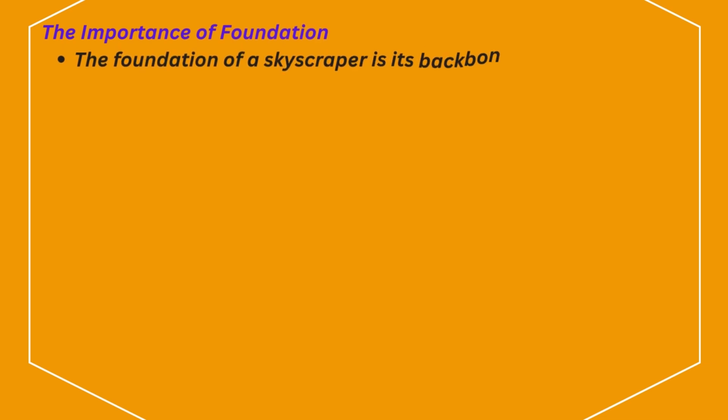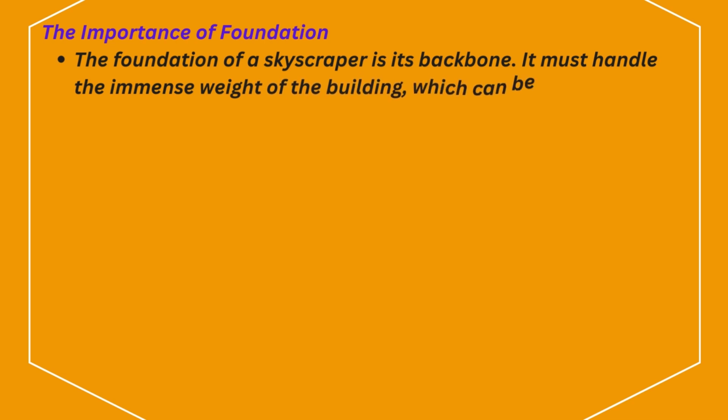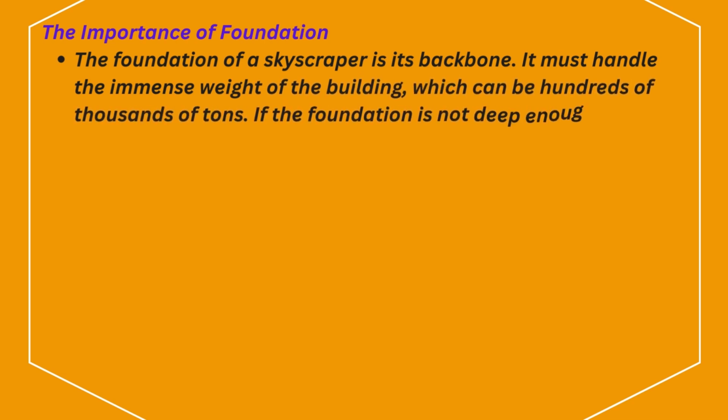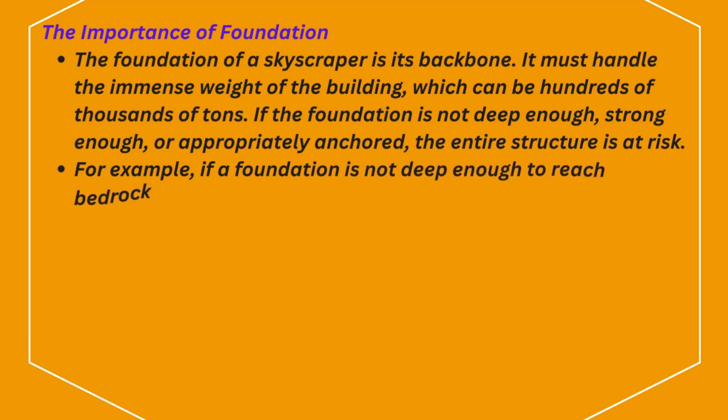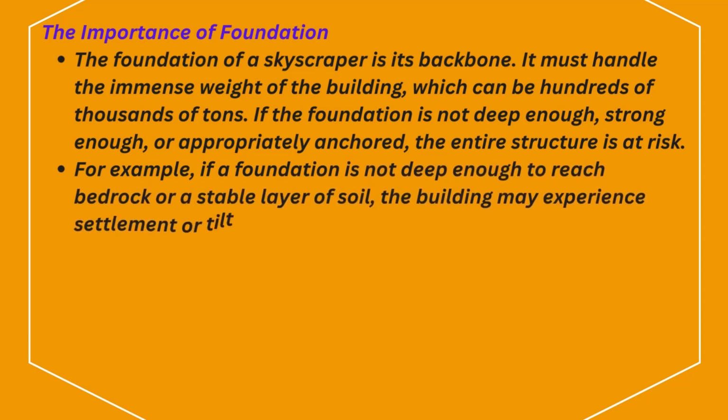The importance of foundation. The foundation of a skyscraper is its backbone. It must handle the immense weight of the building, which can be hundreds of thousands of tons. If the foundation is not deep enough, strong enough, or appropriately anchored, the entire structure is at risk. For example, if a foundation is not deep enough to reach bedrock or a stable layer of soil, the building may experience settlement or tilt.